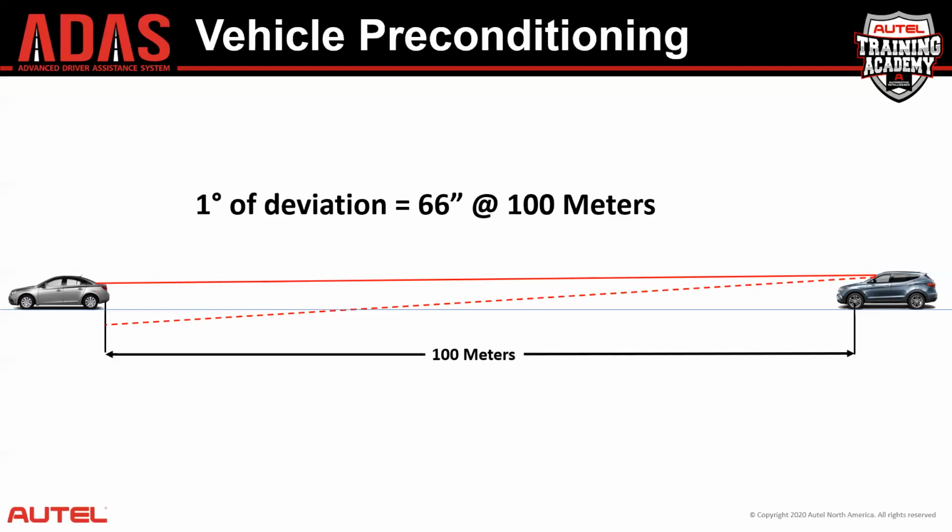However, this vehicle also utilizes the camera for adaptive cruise control, forward collision warning, and automatic emergency braking, along with the radar sensor. The issue that we face is when we calibrated this camera, and it's supposed to be able to see that vehicle at 100 meters, that our radar also detects at 100 meters, our camera is actually looking at the ground at 65 meters and never sees the car. This will cause a decrease in reaction time of critical systems like automatic emergency braking.